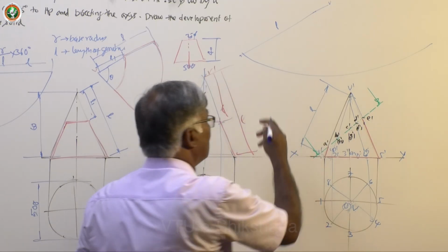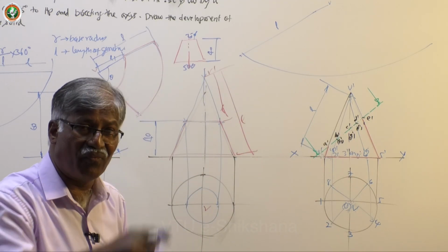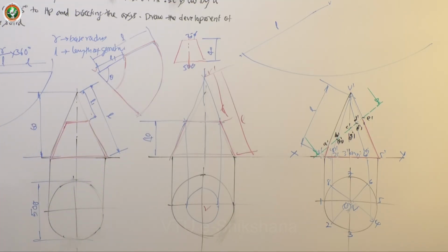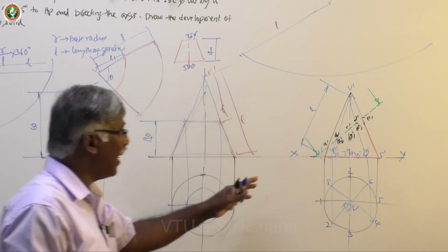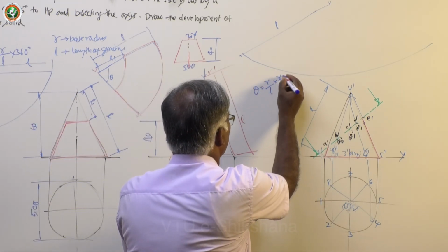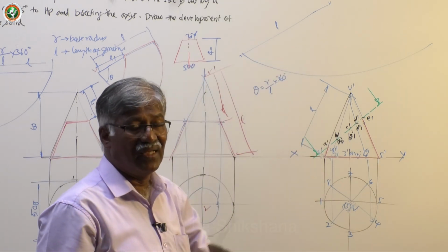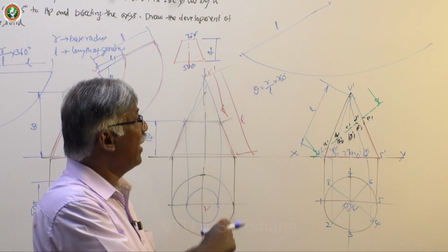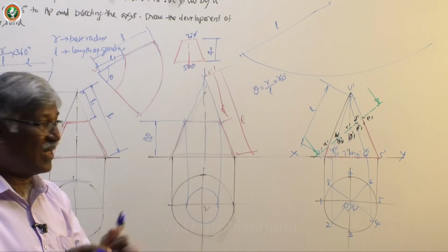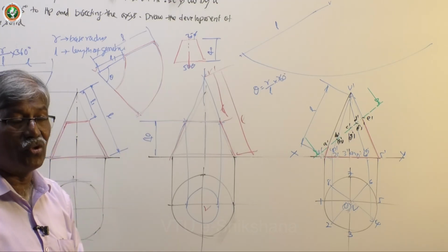Then you can use the circular pattern. In that case, we usually keep for laminate and also for solids the base of the cone as 360 degrees. Whatever value you calculate, theta equal to R by L multiplied by 360, that value you should keep. For example, 138 degrees. You keep 138 degrees. And how many divisions? 8 you have to make, but you add 1 because the number of lines is counted. So, 9 you enter, that I will show you on computer.